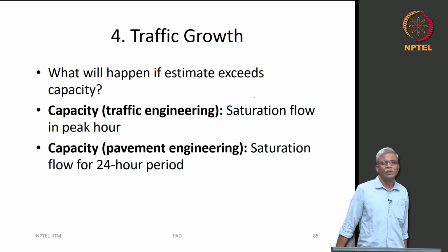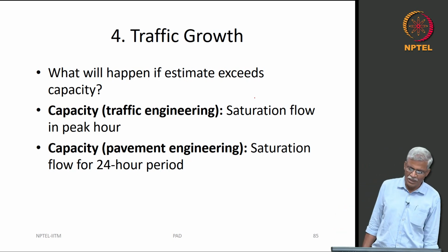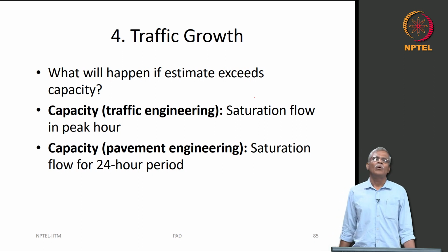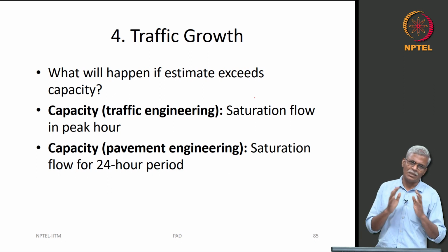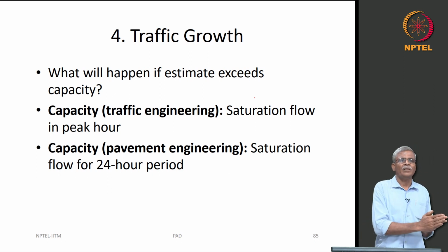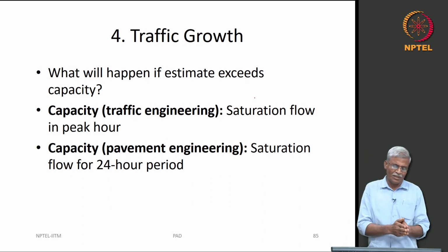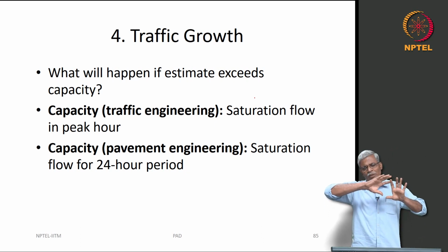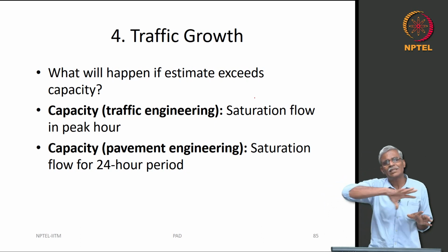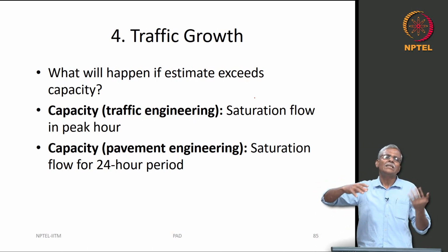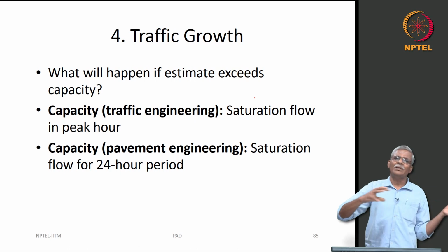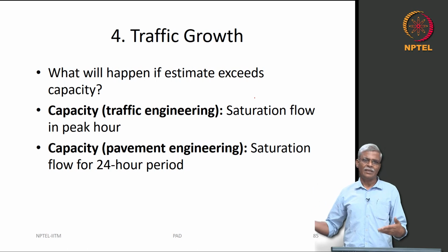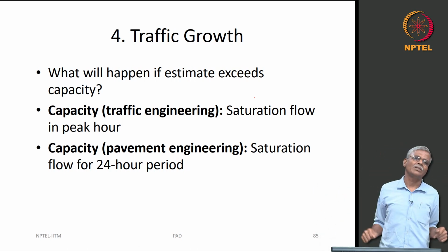Now, the question that you want to really ask is, what will happen if the estimate exceeds the capacity? It can happen. Now, we need to understand how capacity is defined in traffic engineering. Capacity is defined in traffic engineering as saturation flow in peak hour, because you are basically looking only at how this facility that you have constructed is able to service the traffic that is going on it with the least congestion, least delay. That is the whole idea as far as traffic engineering is concerned.